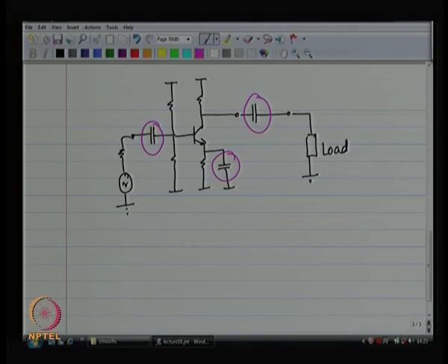These are capacitors that contribute zeros and not poles in the system. If you say that these are large capacitors, I am going to treat them with the OC time constant method, then you will get ridiculous answers, as in you are killing your bandwidth every time you make the capacitor larger, right. That is not the case. These capacitors affect the lower cutoff frequency.